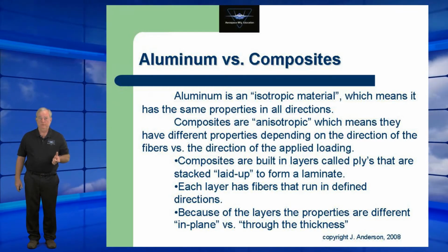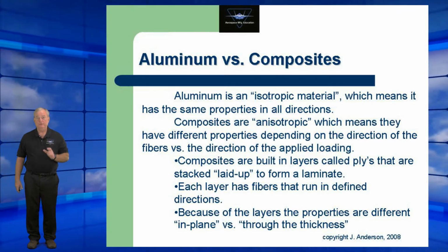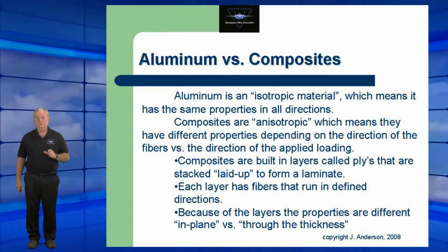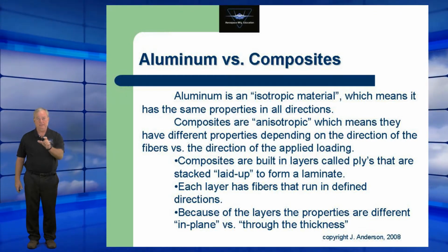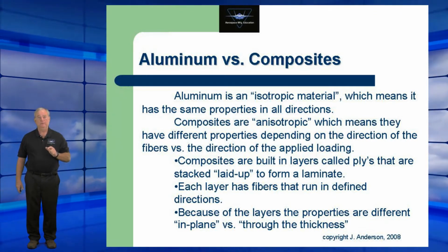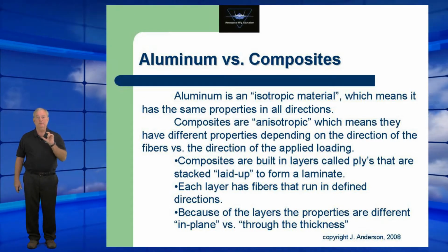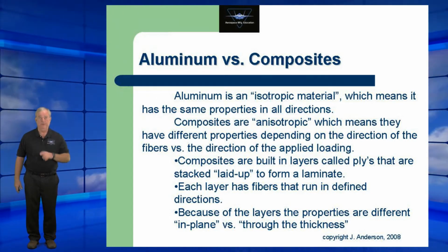Going back to the previous slides on the materials, we said that the strength of the composite comes from the fibers themselves. Those are along the axis; the strength is along the axis of the fibers. So it's very important that we orient the fibers in the direction that we need to withstand a stimulus to failure or a force.